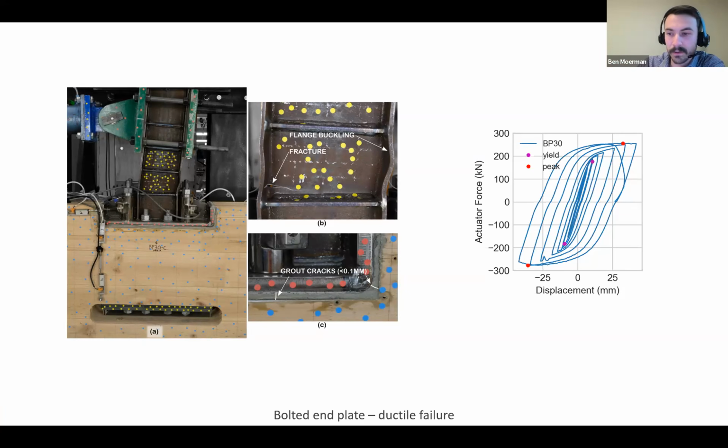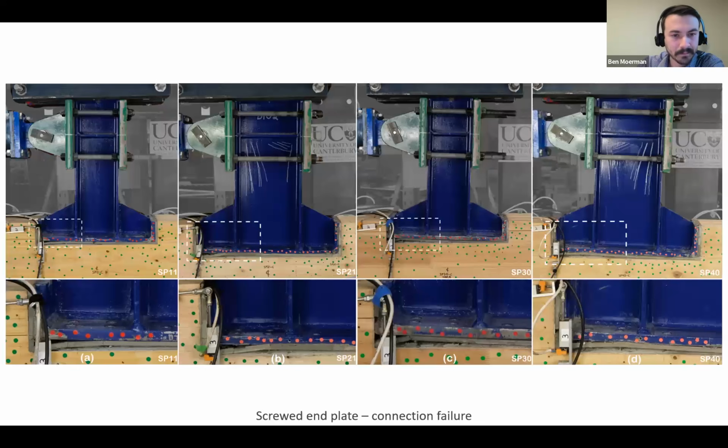We waterproofed the timber so it wasn't leaching out water from the grout. But that way we could guarantee a tight connection, and then in the overall system, we're engaging those link beams right away. But overall in this test, the grout looked really good. Just tiny hairline cracks. And so this test was a success.